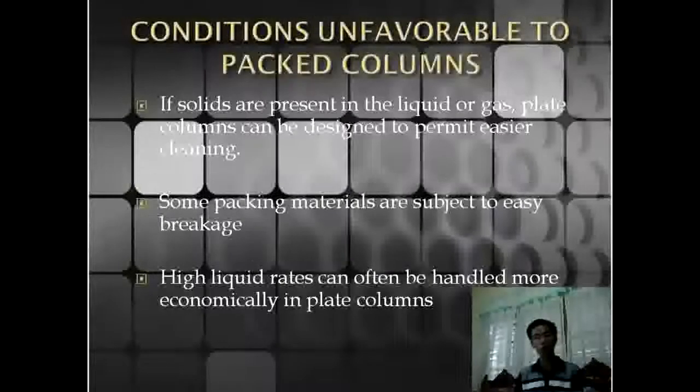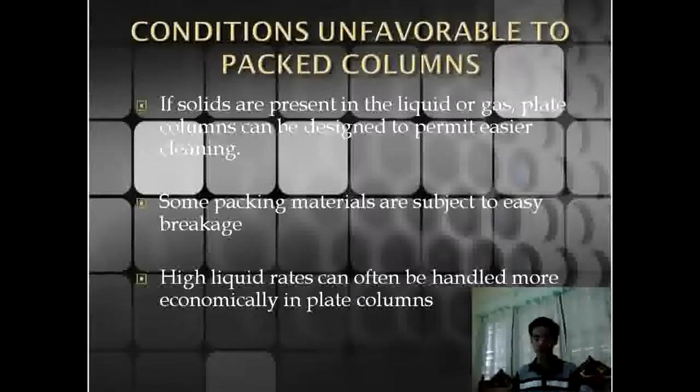Now for the conditions unfavorable for packed columns. Plates are comparably easier to clean than packings. Due to its size and material, packings can easily be broken due to insertion or due to thermal effects. There also is a limit in the velocity of the liquid that packed columns can handle, so high liquid rates cannot be handled in packed columns.